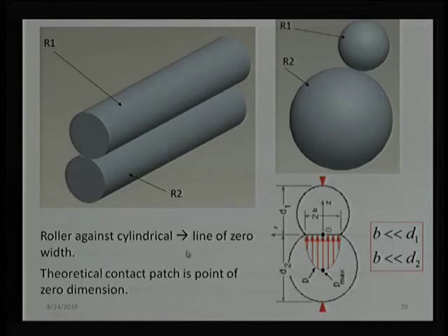And when we come to the sphere, again in many books we say that a sphere on a sphere gives only point contact, but in reality it is not a point contact, it is generally a circular contact, and we need to account for that kind of contact. This is given over here. If the perpendicular dimension is also B or 2B, then it will naturally be a spherical or circular contact, while if in the perpendicular direction the contact patch is 2A and A is different from B, then we can say that it is elliptical contact.